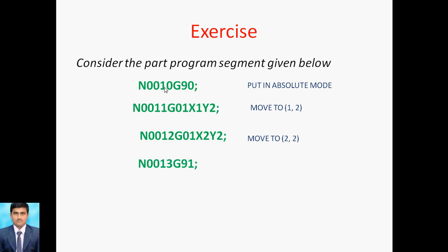Now the next exercise for the program is N0013, the next program sequence. Then G91, which is called incremental mode. G91 is there, so I take incremental mode.